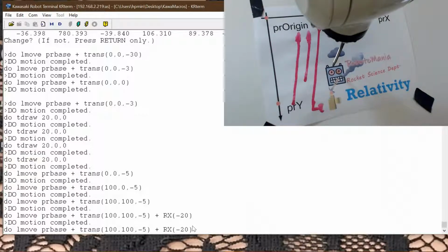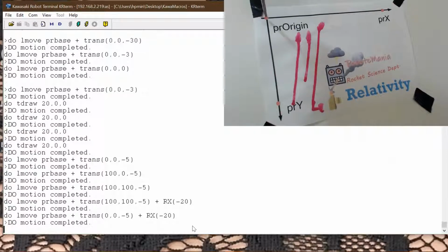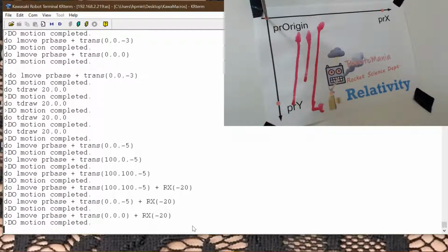Let's go and hit our X position, our origin first. Always check twice. So, there we go. Can I land on my tool coordinate position? Yes, because I defined my tool, and my tool is quite accurately defined. So, sorry, minus 20. I said minus 20. And I will land. Can I land? Let's see. Okay, I did land.